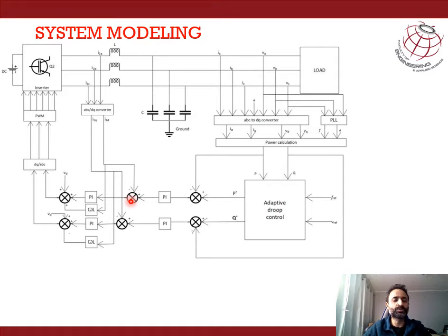controller is also to reduce the difference between the desired current that we have achieved from the right side and the actual current. So based on the current PI output, we generate PWM output pulses which control the firing of the inverters. In this way, we are able to regulate the active power flow into the microgrid, and based on the load fluctuations, the active power flow can be regulated so as to regulate the frequency of the system.